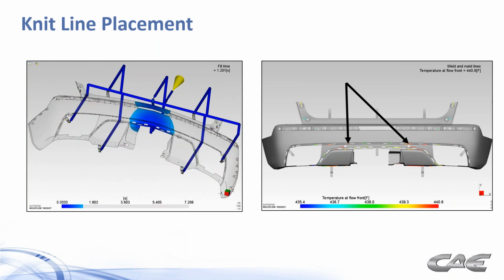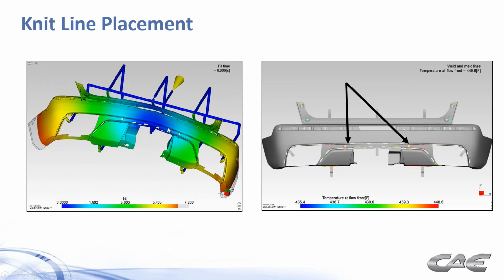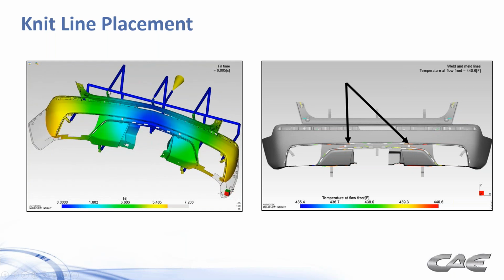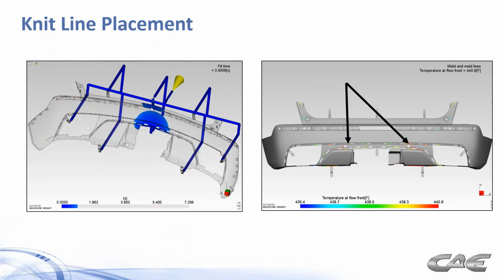So then we get to the mold tryout and we try to start setting this up, and someone looks at the times and tries to set the nozzles up so that they fire at specific times, and then the knit line's off, for example. So when you're at the press, you need to run a short shot sequence study to confirm the precise moment when the flow front gets back to the nozzle. Make sure that you're doing those types of things at your mold tryouts so that you're getting visual confirmation of the filling pattern so that you fire these nozzles at the right time.